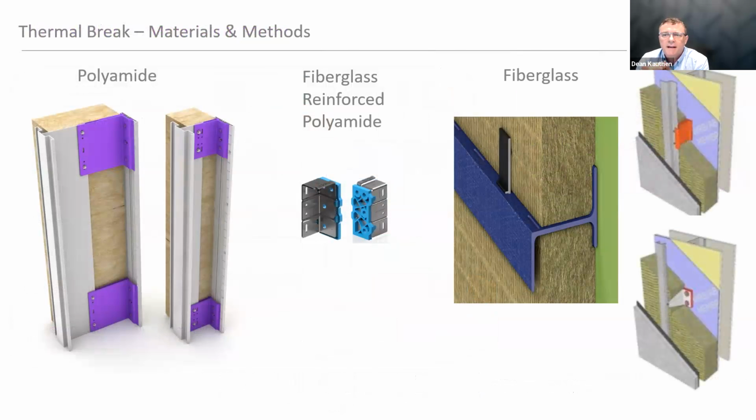So here we can take a closer look at how insulation is encapsulated around the clips that have low thermal conductivity. And this gives you a very high degree of thermal performance. So continuous insulation around the building envelope plus incorporating cladding support systems that use materials with low thermal conductivity offer us the best and most effective thermal performance.